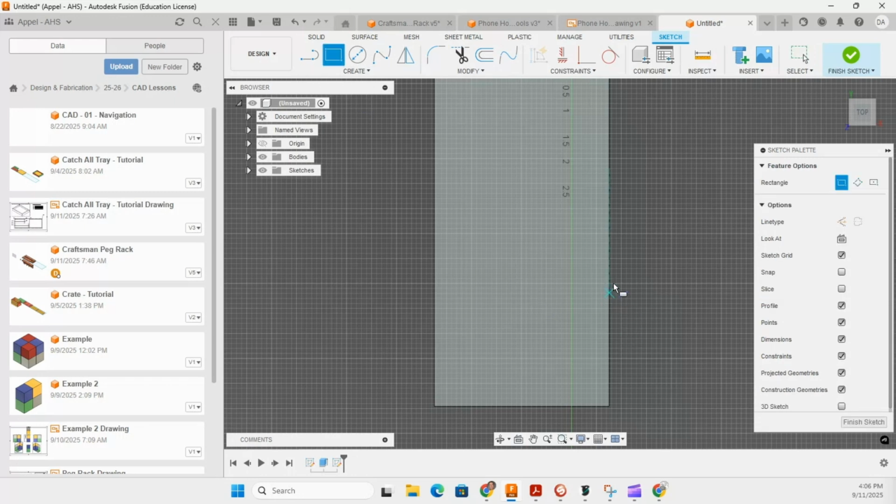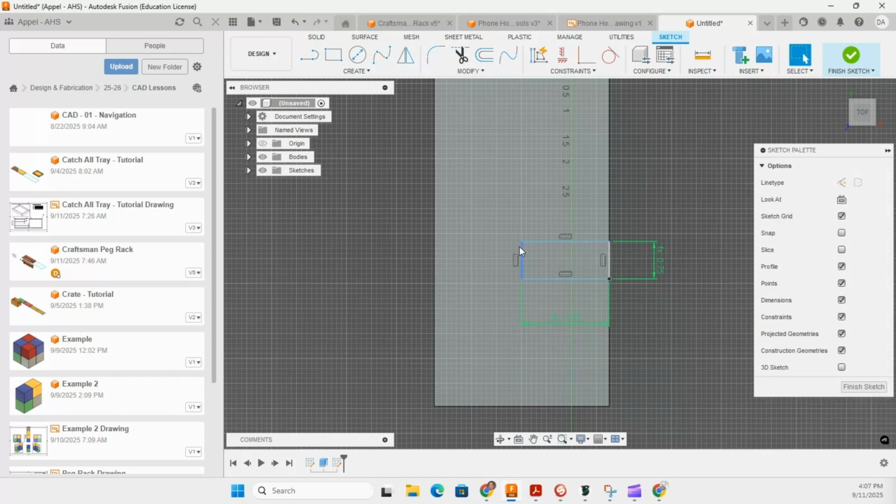It doesn't matter where I start. I'm going to hover down here until I get that triangle. That's the midpoint. See, it brings up that blue line. And I'm going to go the stock thickness. And then this one, it's already set there, but if I change it, this is the width divided by 2. There we go.